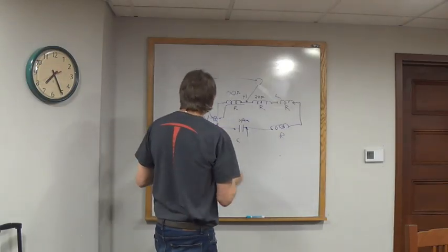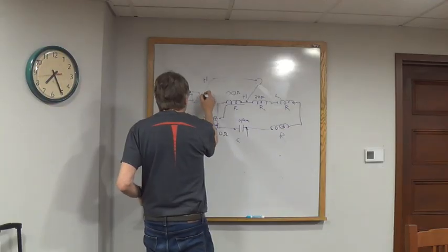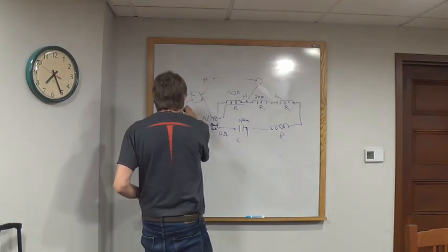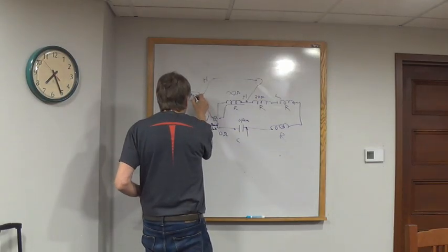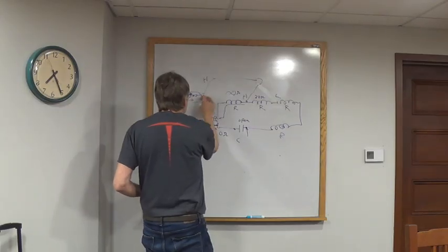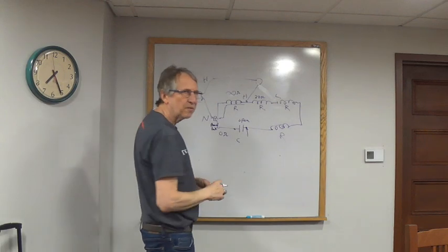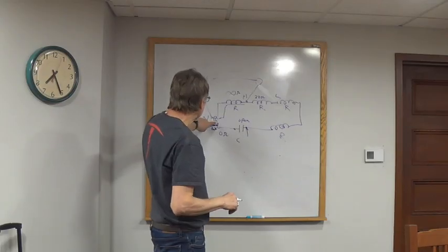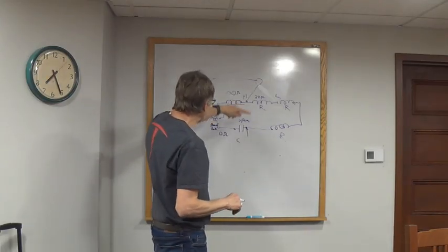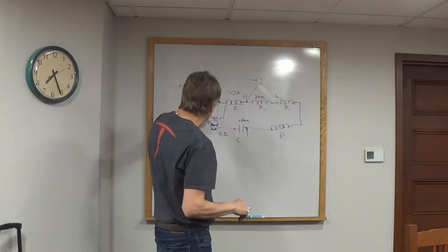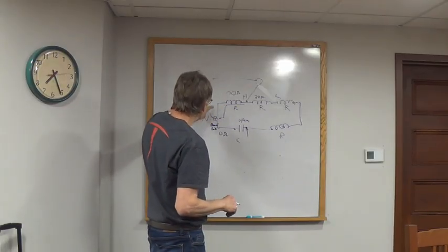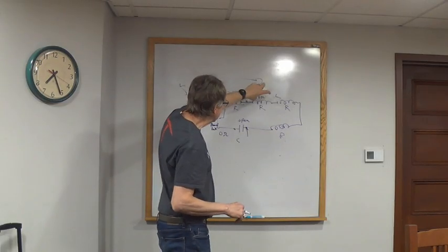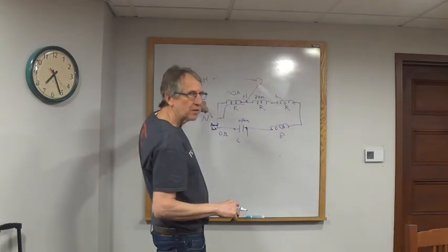burned out. And typically, where your electrical fuse is, which makes more sense, it's here, let's say this is hot and this is neutral. Your fuse is here, so nothing even gets in when the electrical fuse is burned out. And the thermal fuse, it turns out that's like the best place to put it in terms of design, because no matter what's causing the heat, it just cuts the neutral. Now you have a gap here, and no matter where you have the switch, it's not getting back to neutral.